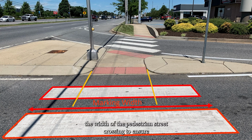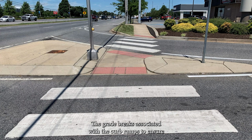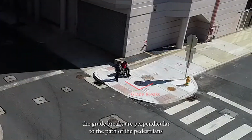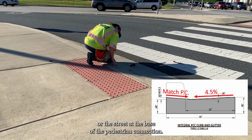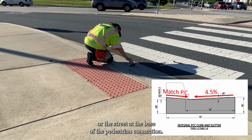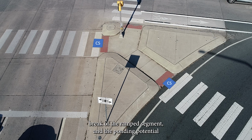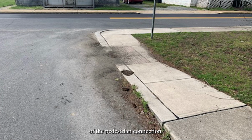Other accessibility requirements of pedestrian connections which will be evaluated during the ADA inspection include the width of the pedestrian street crossing to ensure that the pedestrian connection is wholly contained within the crosswalk markings, the grade breaks associated with the curb ramps to ensure the grade breaks are perpendicular to the path of the pedestrian's travel, the counterslope of the gutter pan or the street at the base of the pedestrian connection, the clear space dimensions at the bottom grade break of the ramped segment, and the ponding potential of the pedestrian connection.